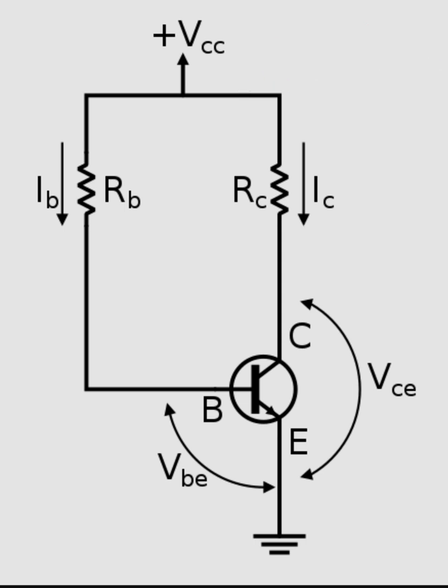So due to the rise in IC and IB, the earlier set operating point is no longer active and the transistor experiences a new operating point. So we see that the stability of the circuit is changing due to the different operating point.